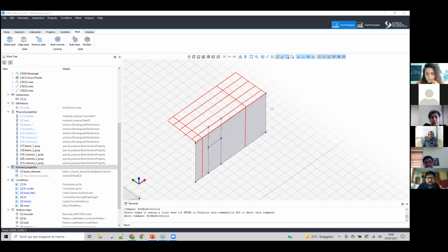So in this case, my slab will be a flexible shell. And in this case, these two red lines that are mimicking the columns should be a force-based element. Yes. And you think that the axis should be in the position of the actual axis of my pier. Yes, and then the beam that you define here, the one that has your spandrel. The spandrel, yes. I couldn't come up with the word in English.